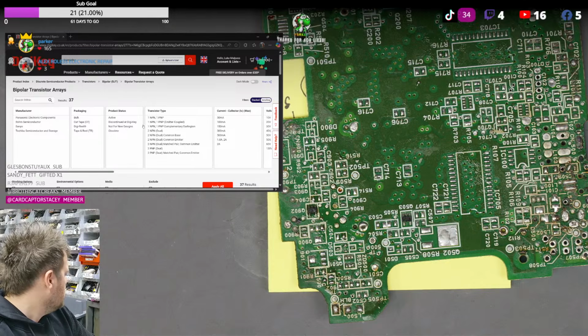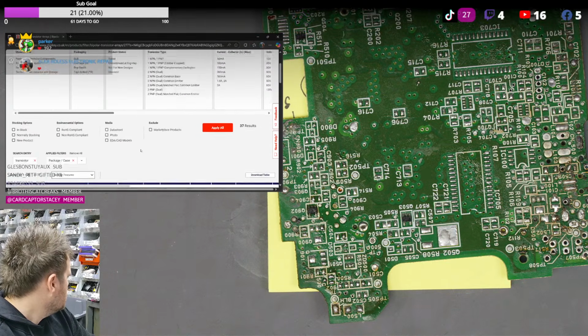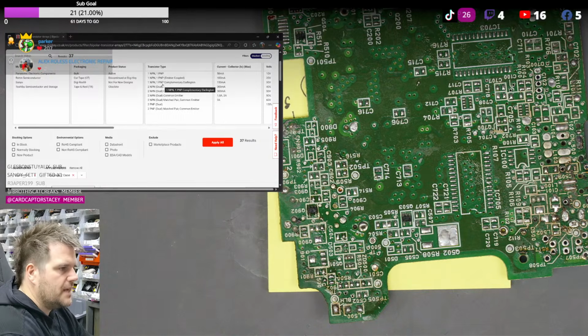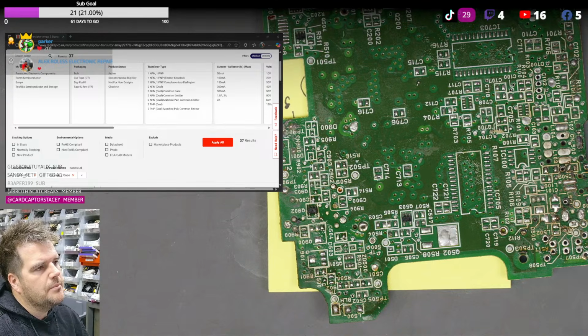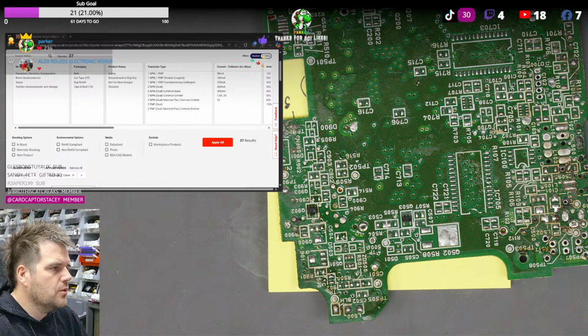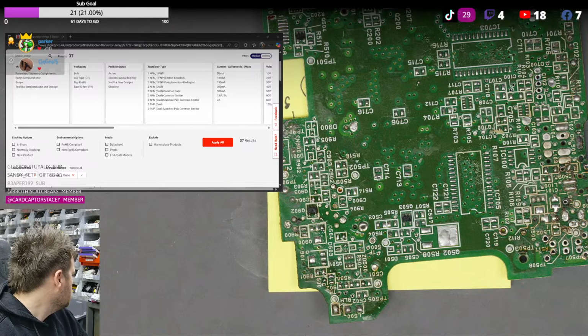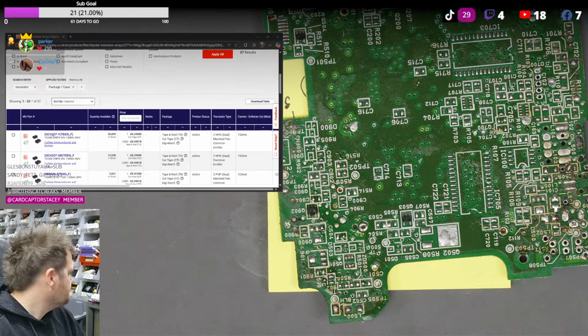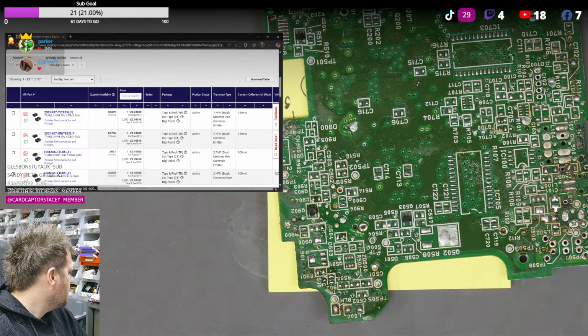So there's various kinds. There's 1 NPN, 1 PNP, two with match pairs, complementary Darlington. I suspect a Darlington would maybe make sense here. I just keep going back to the fact that it's to regulate voltage. So would it be a current mirror? It's not going to be a current mirror. No, it's not going to be that. Let's just look at some of the data sheets. So let's start with a 2 NPN matched pair common emitter.